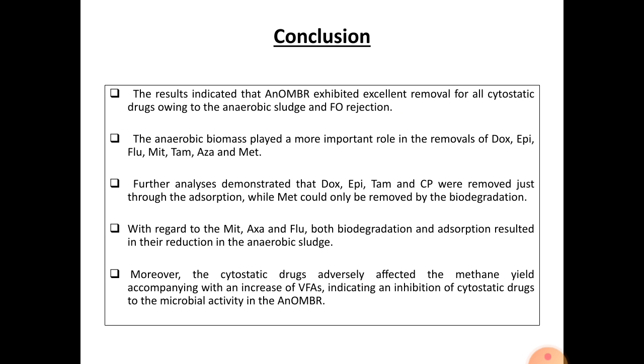So in conclusion, in this study, the anaerobic membrane bioreactor exhibited excellent removal for all the cytostatic drugs, and this removal is owed to the anaerobic sludge and the forward osmosis rejection. The anaerobic biomass played a more important role in the removal of the cytostatic drugs.